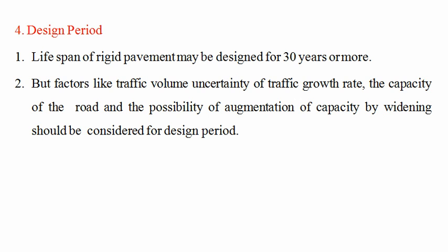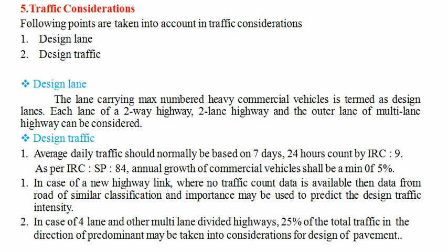The design period. The lifespan of a rigid pavement design is generally taken as 30 years or more, as I discussed earlier. But various factors like the traffic volume, uncertainty of the traffic growth rate, the capacity of the road, and the possibility of augmenting the capacity by widening should be considered during the design period calculations of a pavement.